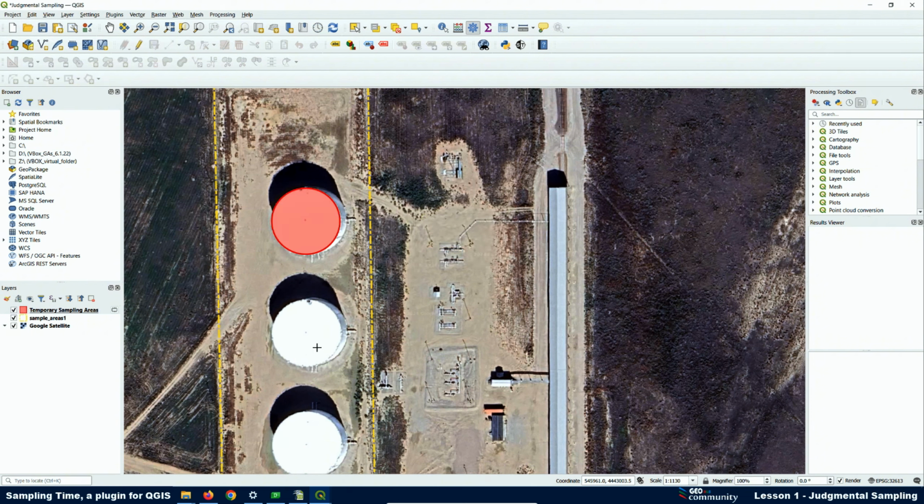Okay. And now I'm going to do the second one. The same, left click on the center. Then set up the radius. If you don't like it, because it doesn't feel really well, you do the same right click, but instead of adding anything, just cancel. And then you can start again. Set up the radius, right click, enter the ID. In this case, it's going to be number 2, and okay.